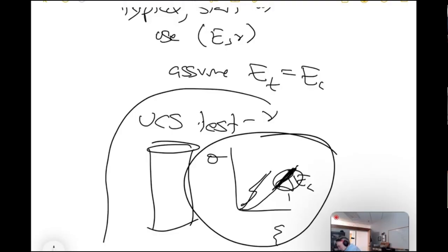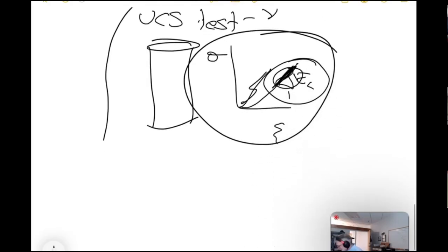We're going to say, can we make an isotropic packing of particles, and can we choose the stiffnesses of the springs such that we can match the E and the nu that we get from a UCS test? That's going to be a typical starting point of all bonded particle modeling, and that's how we're going to start off and try to match deformability. Okay?